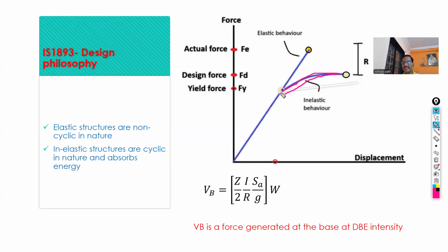While this is the elastic range of the structure, the elastic behavior is not cyclic. It is non-cyclic, so it does not dissipate that much seismic energy. So the focus is only on the inelastic range of the structure. Now, what is the change in performance-based design?